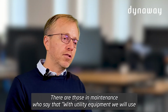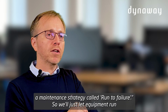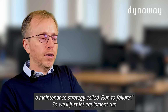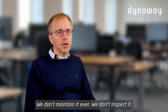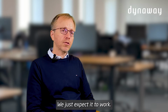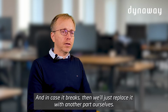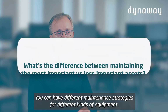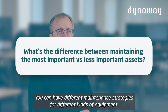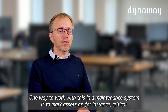There are those in maintenance who say that utility equipment will use the maintenance strategy called run to failure. So we'll just let equipment run until it breaks down or fails for some reason and just replace it. We don't maintain it ever. We don't inspect it. We never look at it. We just expect it to work. And in case it breaks, then we'll just replace it with another part ourselves, or call a contractor and he'll come on site and do it. And you can have different maintenance strategies for different kinds of equipment. One way to work with this in the system is to mark assets as, for instance, critical.